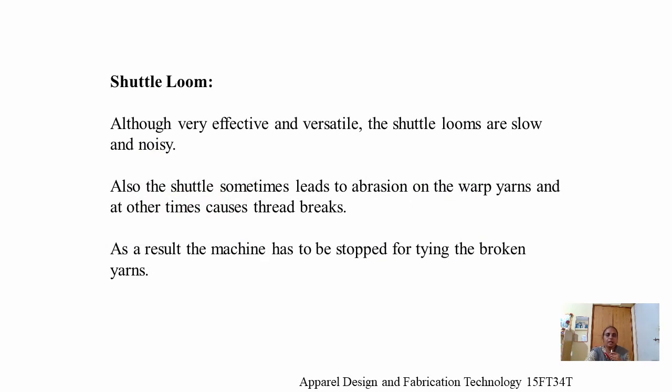Shuttle loom. Although very effective and versatile, shuttle looms are slow and noisy. Also the shuttle sometimes leads to abrasion on the warp yarns and at other times causes thread breaks. As a result, the machine has to be stopped for tying the broken yarns.